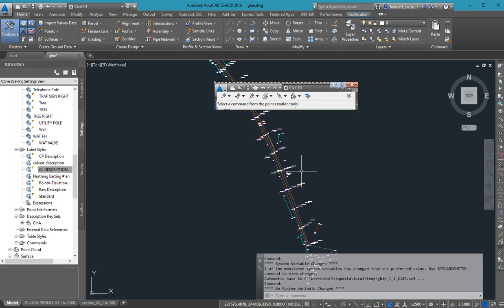It could be that because of visibility, they had to raise it, because we are only interested in the location in plan, not the elevation per se. So the points that we need to form a surface from are normally the cross sections, that's the ground levels. That is why the surveyor also picks ground levels, then the road itself. The road has a road edge, and if you also have shoulders, you include them. Shoulders, road edge, center line, and what? Yes, both edges, the left, the right, and the center.